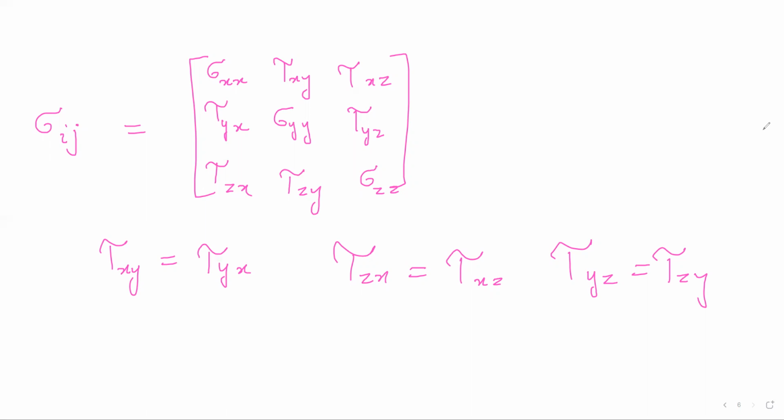When we are considering the x plane, only sigma is used, that is the normal stress. Whenever we have a normal stress, we will use the word sigma. Whenever you have shear stress, we use tau, although even here, if you want to use sigma instead of tau, it is acceptable, because in textbooks and reference books they use sigma here. But even then you need to know that with xy or xz or yx, that's still a shear stress. Putting a sigma there does not make it a normal stress.